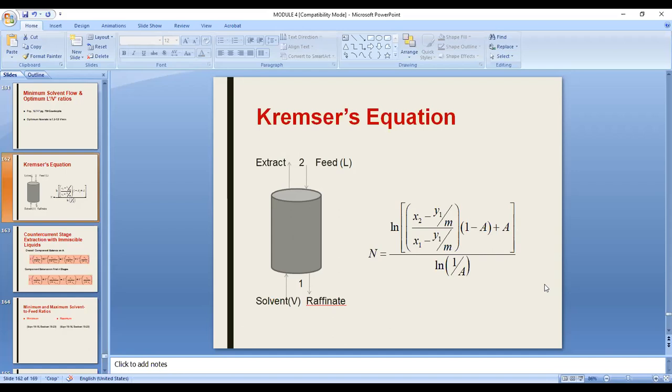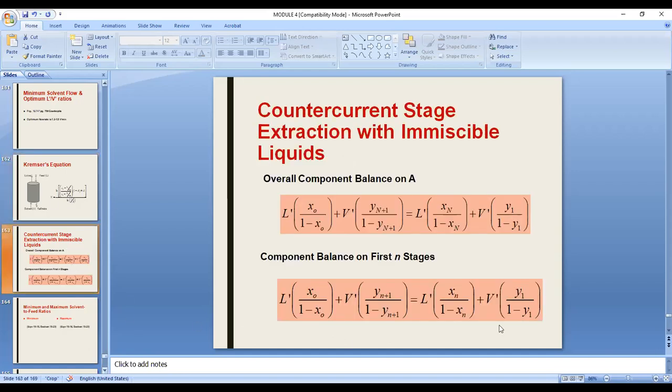Comparable to the opposite of gas absorption, which is stripping. But in principle, it's just the same. It's just the opposite. Now, just like in stripping, I'd like to use the term stripping, you can also use the inert amount of the strips. So L prime for the inert, or that's the carrier solvent of your feed, and the V prime, that's your diluent in your extractant. Okay, that part, the inert part of your feed and solvent phases in extraction.